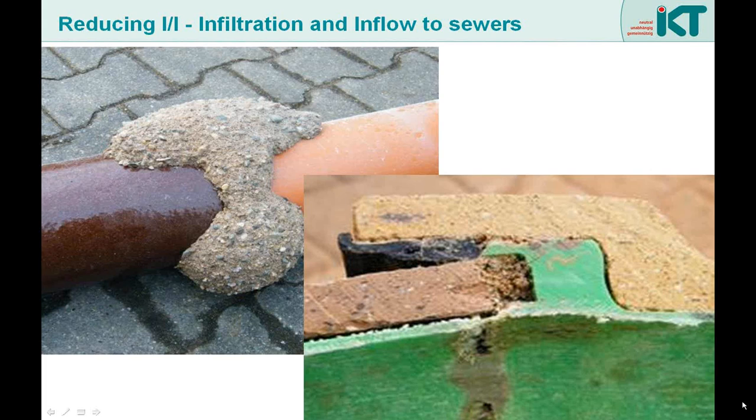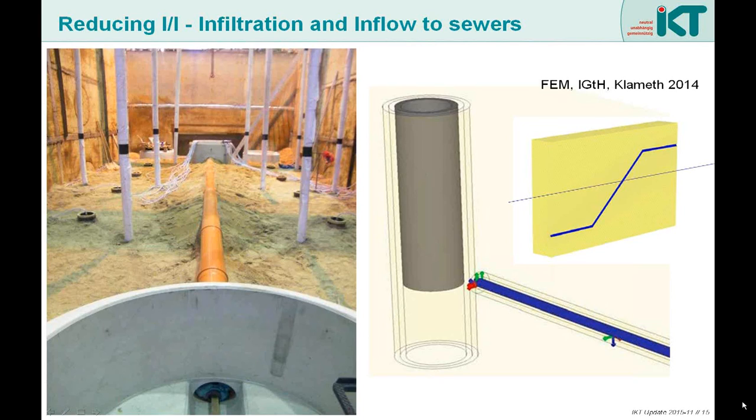You could say the liner becomes a victim of its own sealing success, as the groundwater is rising and uplift effects threaten to damage the liner again. We checked this effect in various measurements and finite element calculations. The sensitive areas are especially at the entrance to the manhole and at bends, but also at variations in the depth of the sewer line, which is a particular issue for house connection lines.